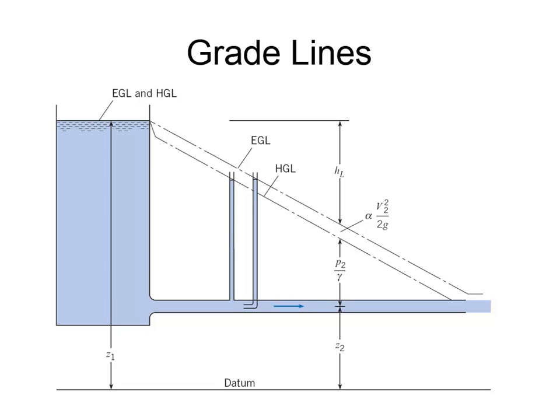as the stationary water that was in the tank speeds up, there's a reduction in the pressure so that it can gain velocity. And so where that line is dropping down, that's just representing the reduction in pressure as the velocity increases. What they really maybe should have, yeah, I guess they're drawing it in the part of the pipe that's curved. Because in the pipe where the pipe is curved, you've got zero velocity and then it's increasing.